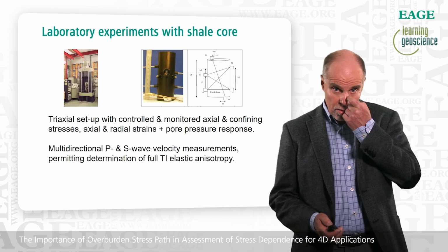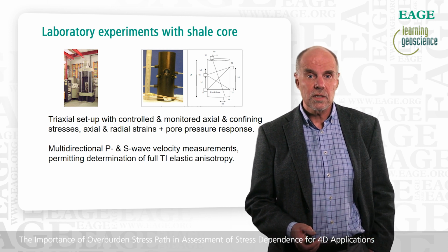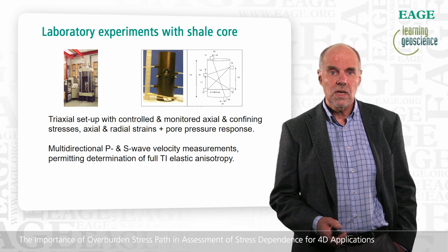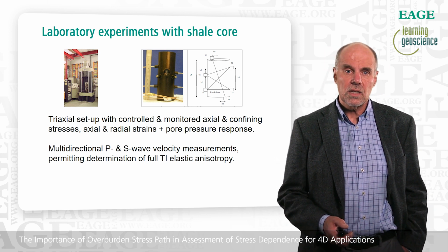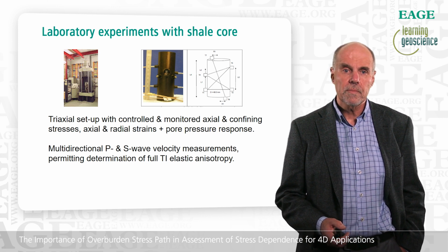So I will now turn your attention to some laboratory experiments that we did. They were done in a triaxial setup with controlled and monitored axial and confining pressures. Axial strains and the radial strains were measured, and the pore pressure response was recorded.